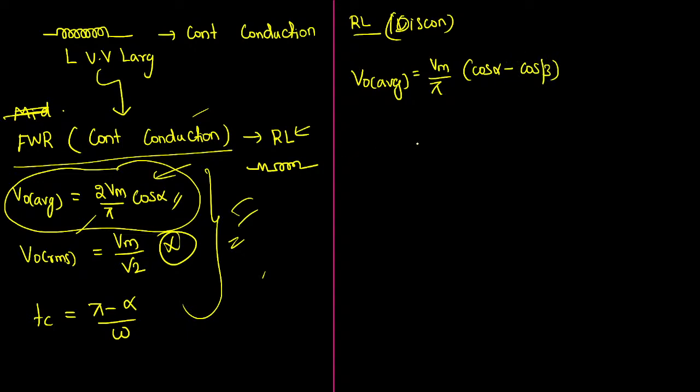Okay sir. The next question they will ask is power factor. Power factor, as usual, you can write the input power factor formula. It is very important here. Current will get cancelled. You can simply find the output RMS voltage and input RMS voltage. Substitute the output RMS voltage and you will get the answer.